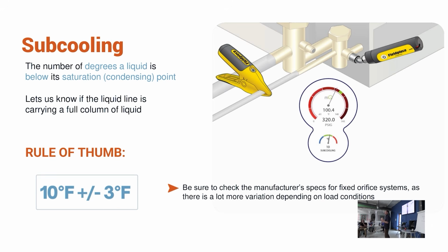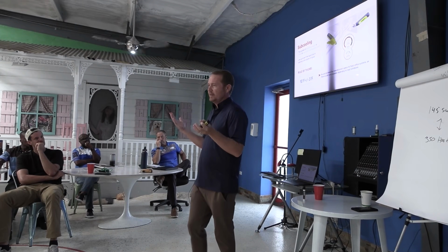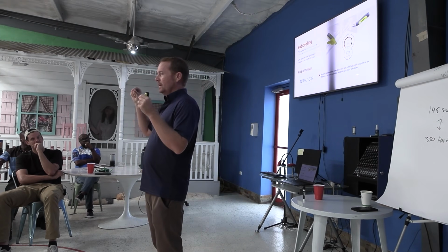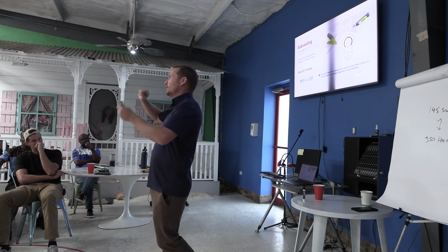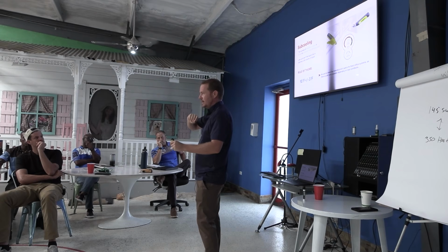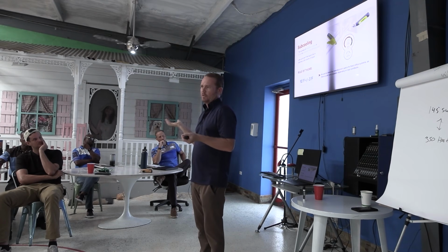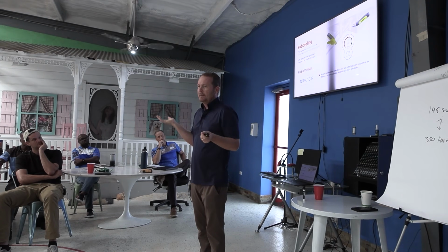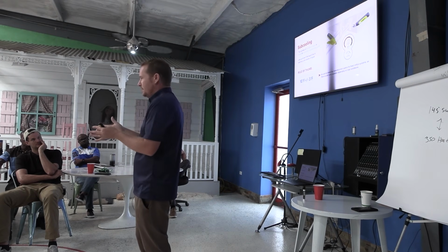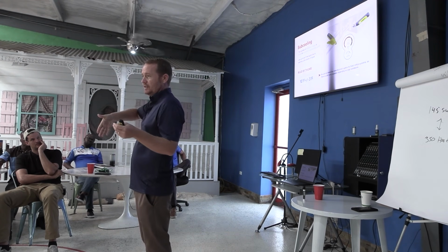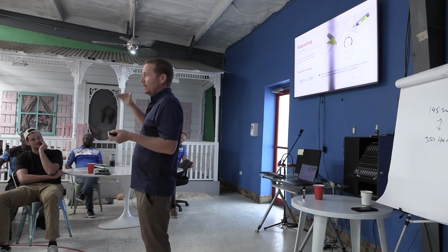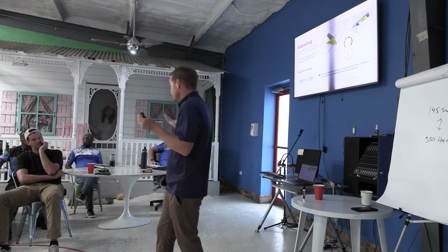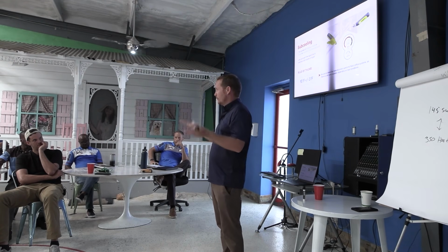And even if your airflow is not perfect, subcooling will still pretty much be okay. It'll still be in the same range. That's an argument that Jim and I have, and we talked about this a little bit yesterday with some of the apprentices: can you tell if your airflow is good based on your refrigerant pressures? And the answer is, yeah, sorta. You can kind of tell. If you have a system where all of your 5 pillars are lining up, and your suction saturation temperature, your evap temperature, is just low, that's an indication of low airflow. And if it's in proper range, it's a pretty good indication that your airflow is pretty good over the evaporator coil. But you have to use those in conjunction with each other.